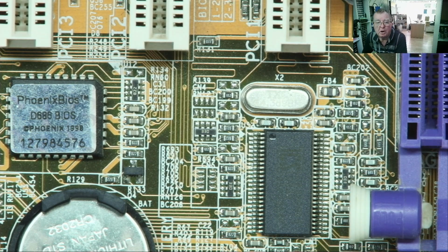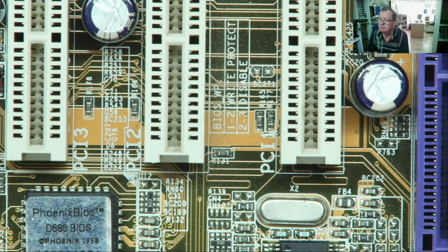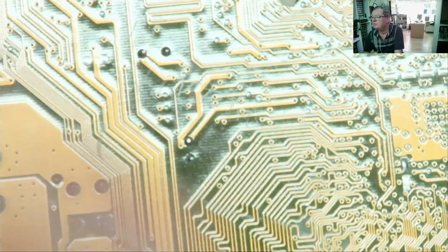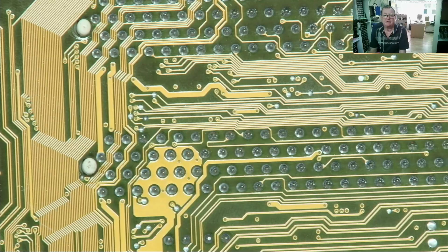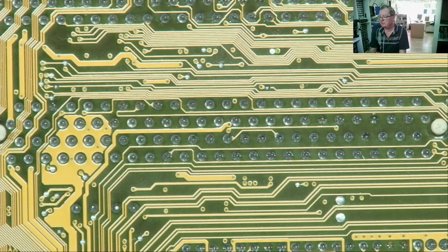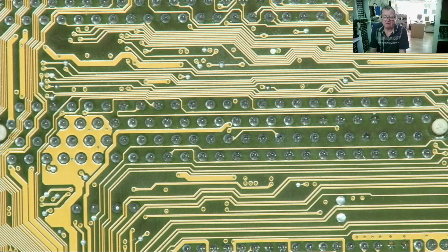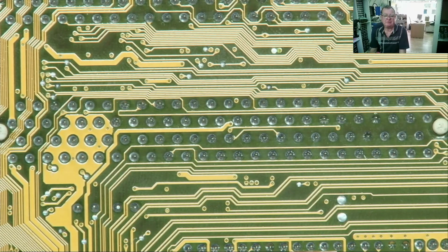And the other common failure with resistors is physical. Sometimes, especially surface mount ones, they just get broken, they just get knocked off the board. Especially in the case of boards like this one, a motherboard, or even more so a graphics card, where there are also a lot of components on the back of the board as well. If it's not been stored properly, it's been kept in a box or something, or suffered some other sort of abuse, you'll often find those sorts of small resistors just broken off the board. So that's the other most common place that you'll find faulty resistors.